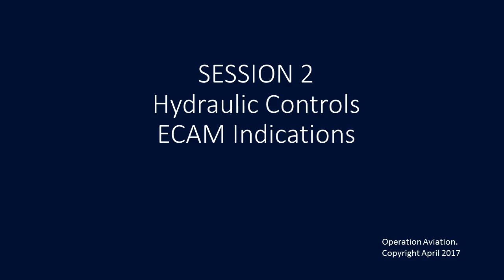These are color coded, so you'll see them on the display, with green indicating engine 1 pump, the yellow color for the right engine, or engine 2 pump, and blue for your electric pump. You also have your push button switches for the PTU, that's for green and yellow, and then for the electric pump, there's another one for yellow, and then your RAT MAN ON, that's your manual. So that was the 40 VU.